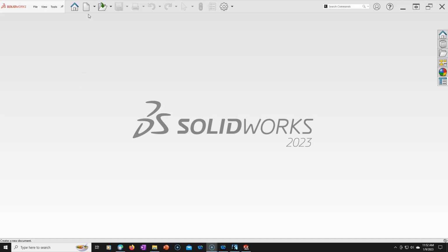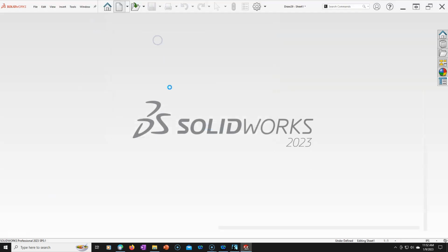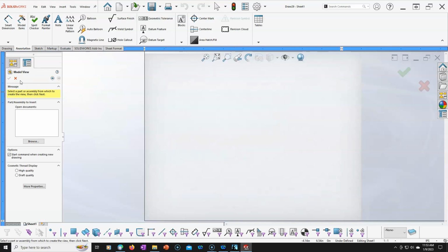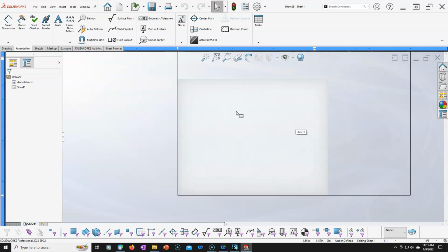We're going to do a simplified drawing template with manual entry. So if you're on the standard sheet, we'll come down to custom size. My practice one I left in millimeters. It got a little bit small. So 8.5 inches. So 11 by 8.5 for the height. And we're not putting any geometry in, so we'll zoom to fit.